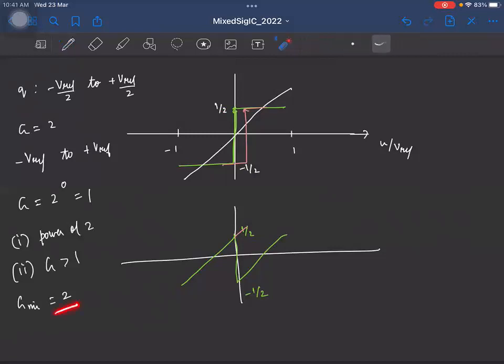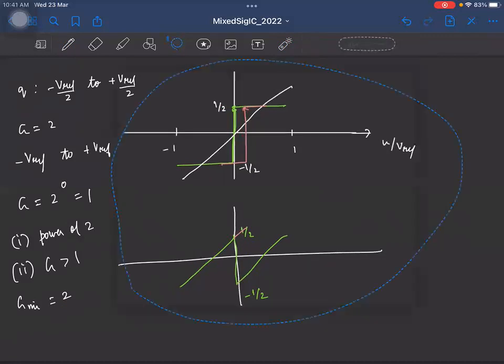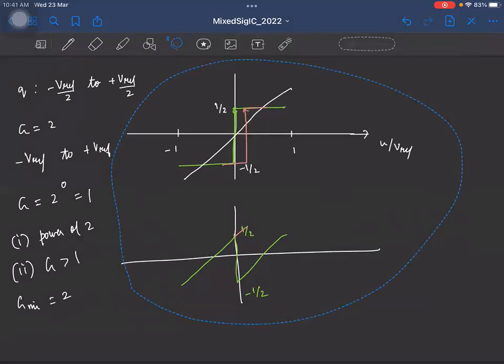But again, if I use a gain of 2, if there is a mismatch in this level, it's going to get overloaded, right? That's fine. So what people do is, instead of having a 2-level quantizer, that is a single bit ADC like this, let me copy it. You can do it, but again, you can't exactly correct it, right? There will always be some error that is remaining. You can't completely cancel any error. In principle, if you want to do any kind of cancellation, that's not going to work completely. There will always be some residual error.